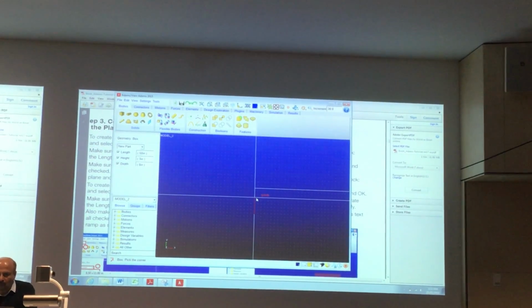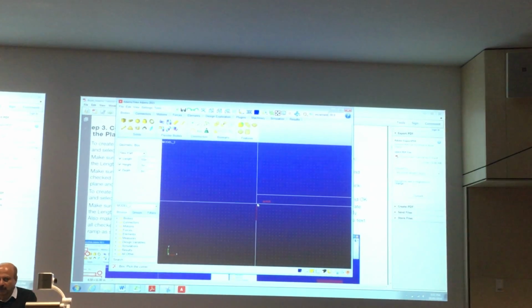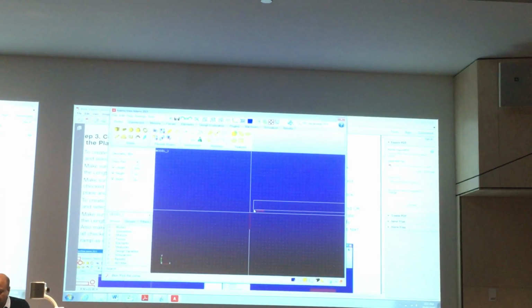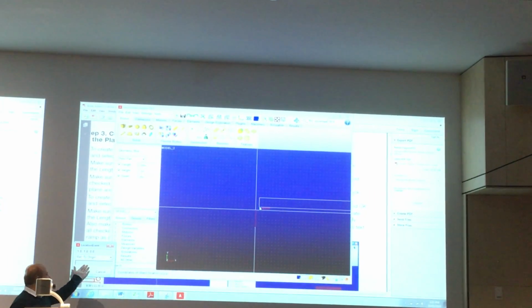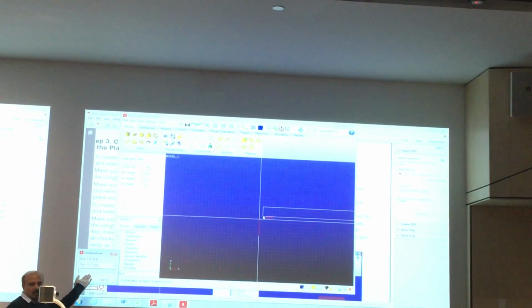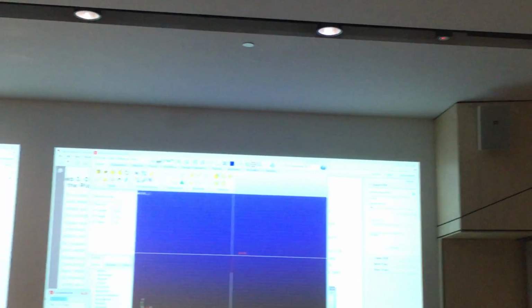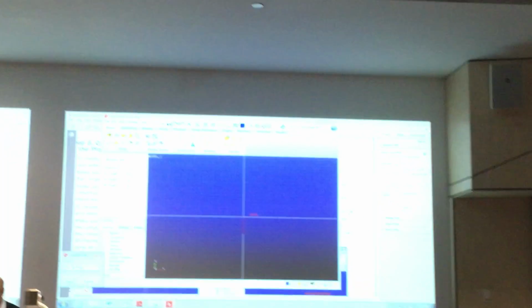So now, when I come back to this, I can just left mouse button click and then also make it work. Otherwise, I can right click here, and then you can see the location comes up here. The window location comes up, and then what I do, I change to 0, 0, 0, and then just say enter.